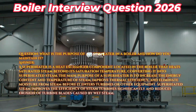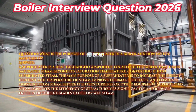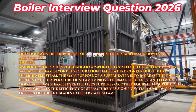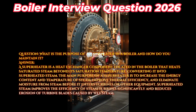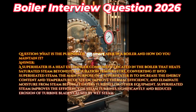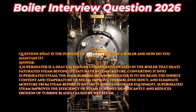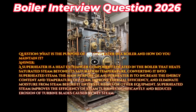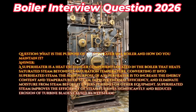Answer. A superheater is a heat exchanger component located in the boiler that heats saturated steam beyond its saturation temperature, converting it into superheated steam. The main purpose of a superheater is to increase the energy content and temperature of steam, improve thermal efficiency, and eliminate moisture from steam before it enters turbines or other equipment. Superheated steam improves the efficiency of steam turbines significantly and reduces erosion of turbine blades caused by wet steam.